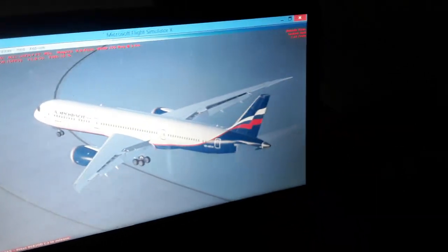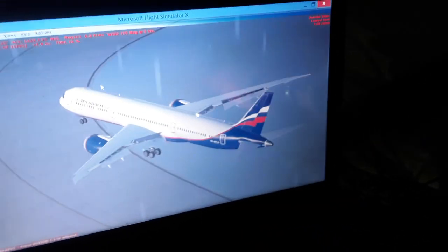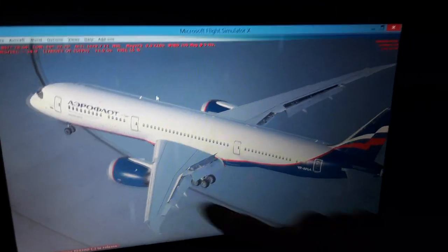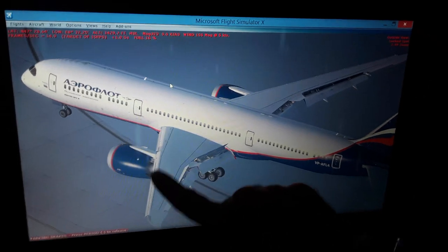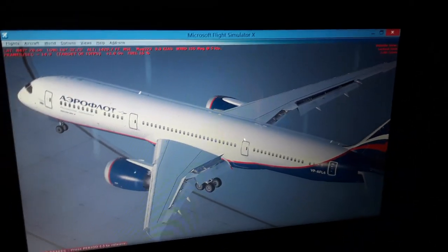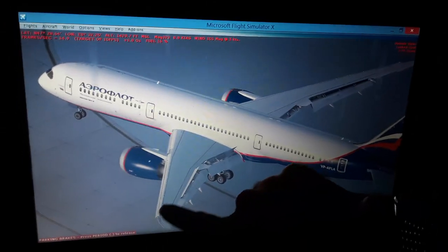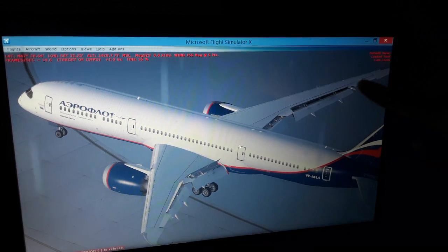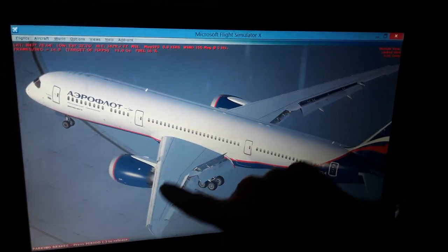So it's very simple. You can see here we have the aircraft. You can see the aircraft wings hold the weight of the aircraft as the aircraft will be flying using the aerodynamic lift over the surface area of the wings. You can see the mean aerodynamic chord position pretty much is 23% of the mean aerodynamic chord. It's where the maximum aerodynamic lift occurs in the forward wings.